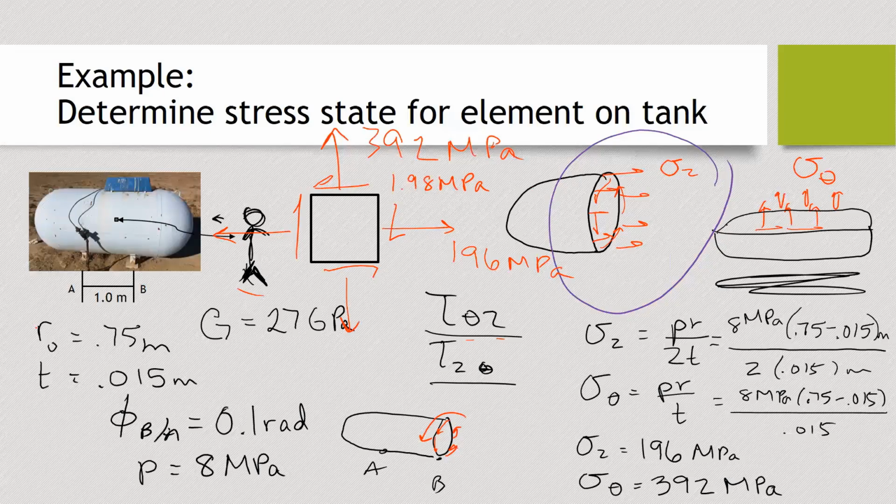So you could cut a second cut, really at any plane through here, and this side here is that second plane that I would be cutting, and this right side would be the first cut, the cut near me, where I'm showing that torsion creating an applied stress onto the material. And then the reaction is what's holding that material onto the rest of the material, and it's going to be going in the opposite direction. So you're going to get this reaction to that applied stress on the backside.